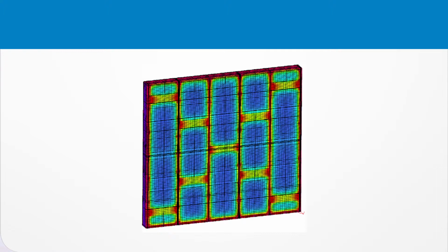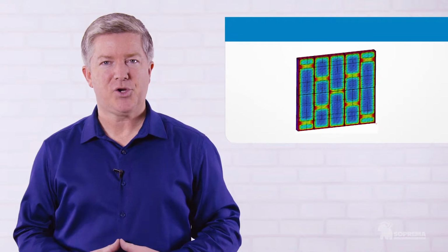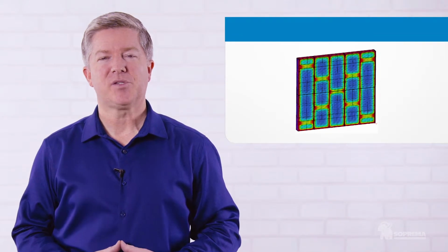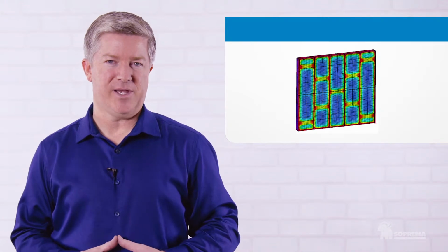And at this point, we understand that there is a greater amount of heat that comes out of this wall assembly because of the poor thermal performance of the steel studs. The U value is the overall thermal transmission. To determine the U value, one can take this assembly and cut it into multiple small sections, creating a grid.